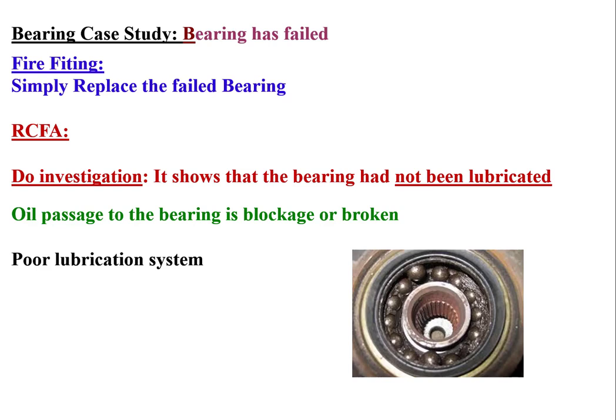In that case, they repaired the symptom. But under reliability, we apply root cause failure analysis. Yes, we will replace the symptom. We replace the bearing because the symptom is the failed bearing. But behind that failed bearing there might be misalignment. There might be improper installation. Even the bearing itself might not be the proper type, or the installation clearances are not properly controlled, or whatever the cause of the problem. In that case, we will eliminate the cause, and at the same time we repair the symptom.